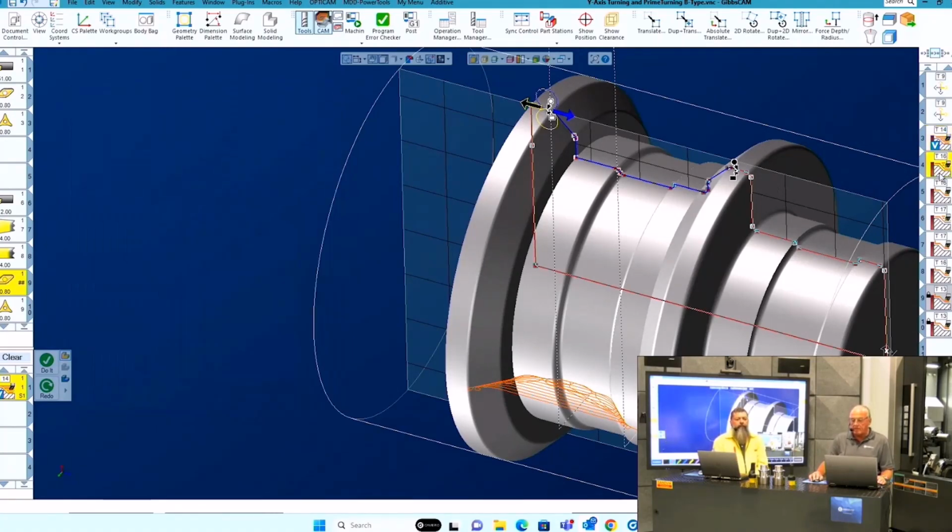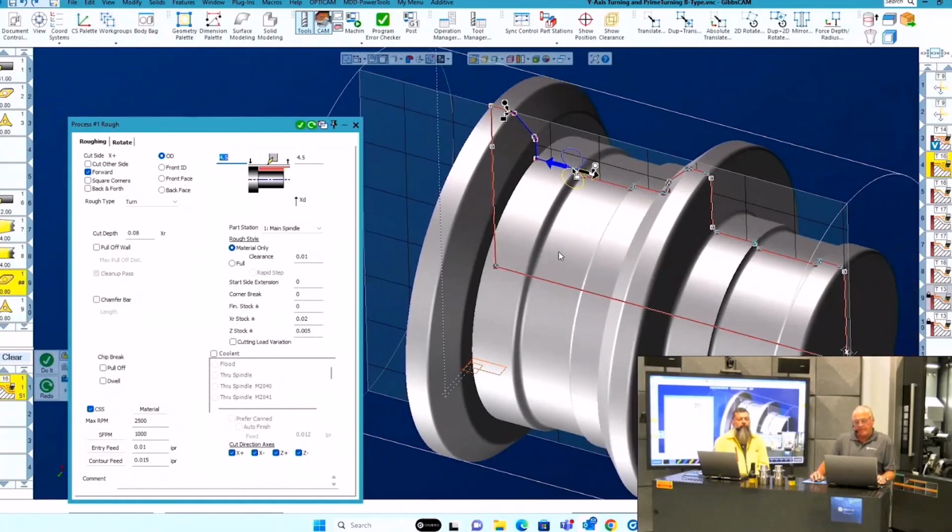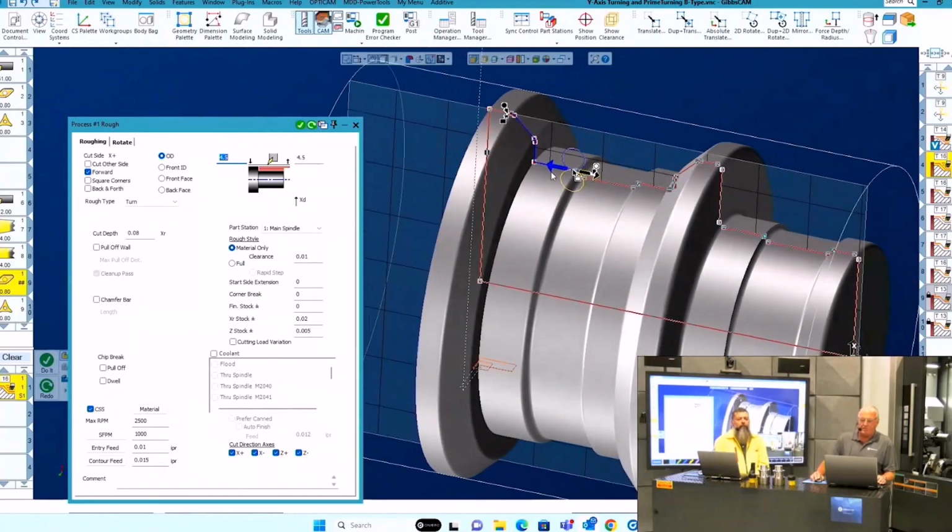And so quickly, I'm now cleaning up down the corners where our round insert left some stock. And as you can see here in GibbsCAM, we have an option that says material only. So no matter where I set my machining marker, they're actually set down here, it defines another area or longer part of the geometry.